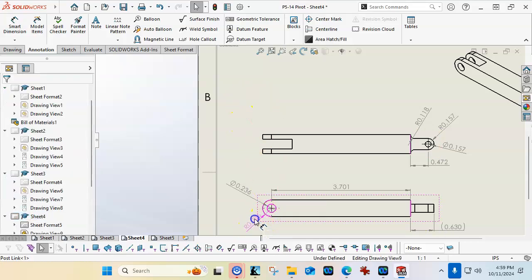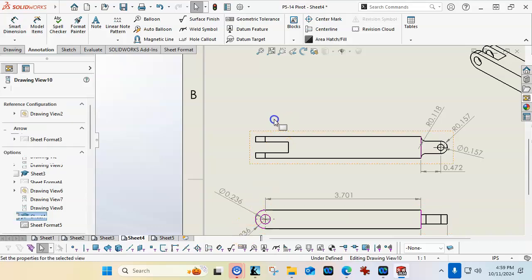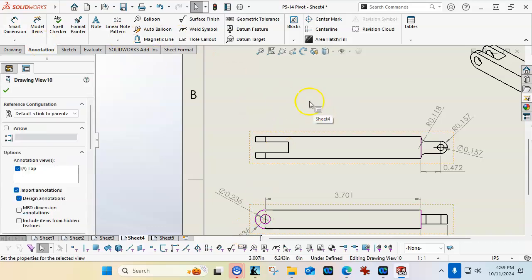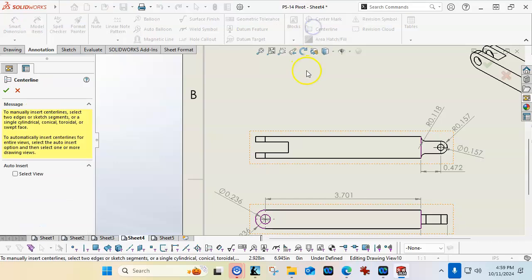Problems with the radius is if we look at the stack up of the tolerance, we're giving this width more tolerance if we drive from the radius. So as we think through that process, it's probably not very critical on the width.